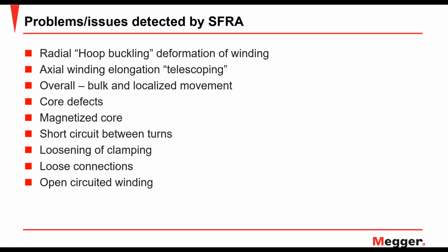Axial, on the other hand, if there is even a minor imbalance in the ampere turns, that can result in significant axial movement of the windings.